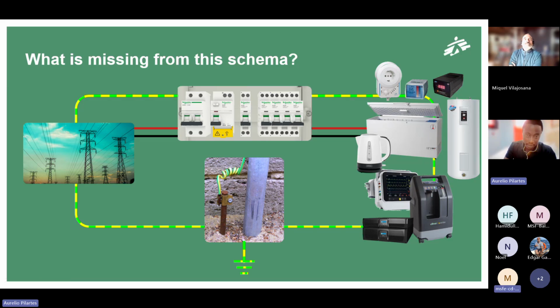It's advised to have 25 millimeters in this scenario. So you have 25 millimeters going from here to the cutting bar, if it's going to feed a main board, a main installation board. We can have other cases with smaller sections. For example, grounding going to the frame of a PV panel could be smaller than this one, depending on the size of the PV panel, of course.